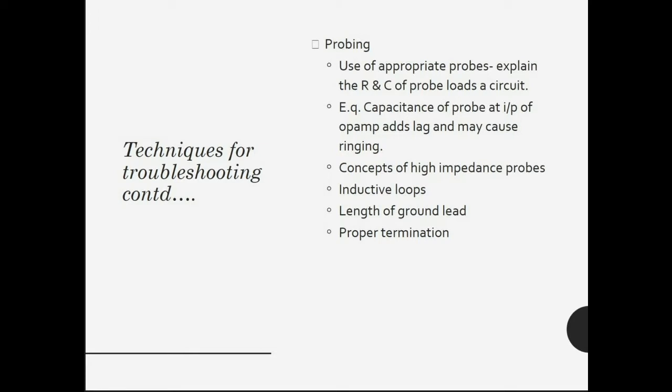Active probes use specially developed integrated circuits. By placing these chips right at the point at which the signal is probed, the signal is preserved during its transition from the point at which it is sampled to the oscilloscope, in some instances using differential techniques. In this way, the signal integrity is maintained despite the fact that it may have a fast rise time, may have a low signal level, or require high input impedance at the point at which it is sampled.